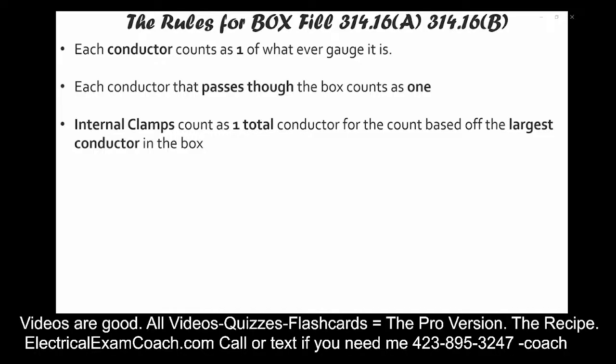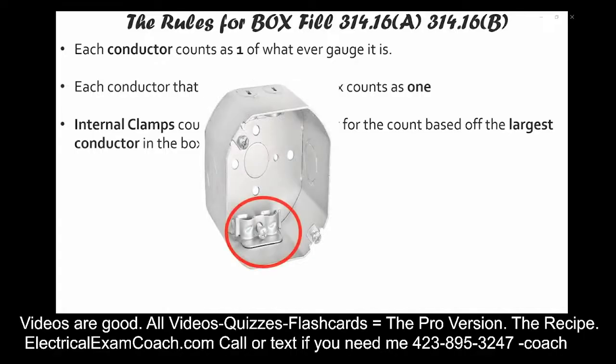Let me show you what I mean. This is an internal clamp. The clamping mechanism is inside the box. Well, it's taking up some of my space, so we have to account for it somehow. What this code is stating is it doesn't matter if I have 1 or 5 of these clamps, we're only going to count it as 1, and it's going to be grouped with whatever the largest conductor is in the box. Meaning if I have 12 and 10 gauge conductors inside that box, this internal clamp would count as 1 10-gauge conductor. All of the fittings we're going to convert over to conductors, then the conductors we're going to convert over to cubic inches, and you'll know more of what that means as we go through this lesson.